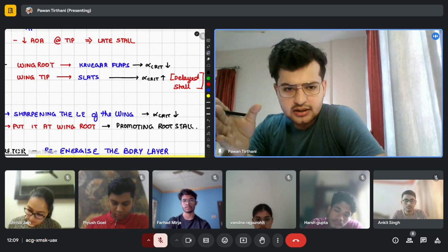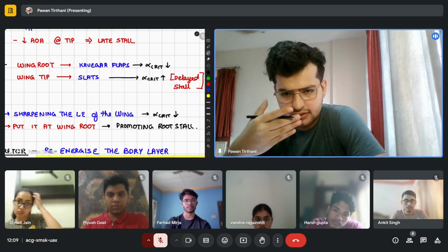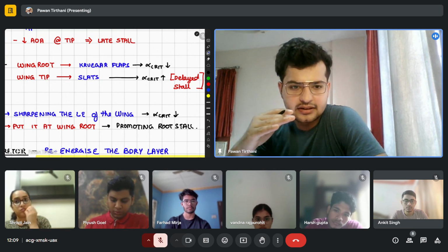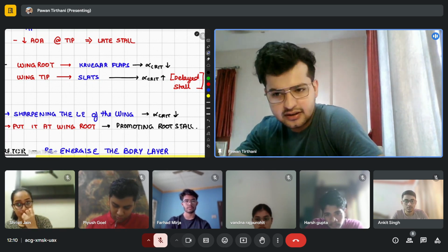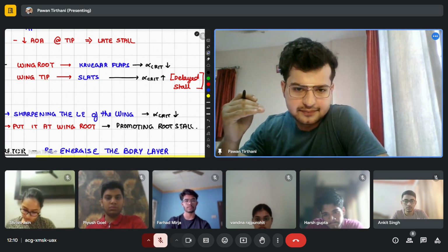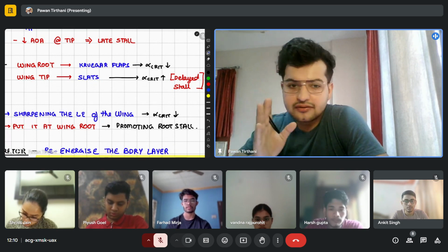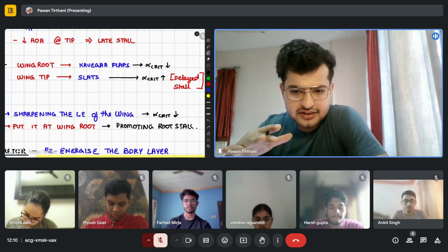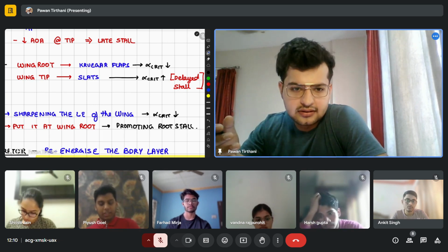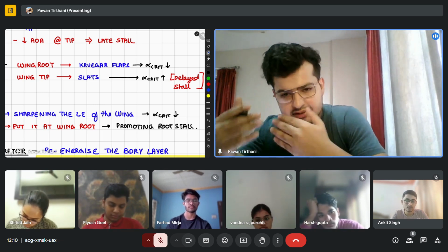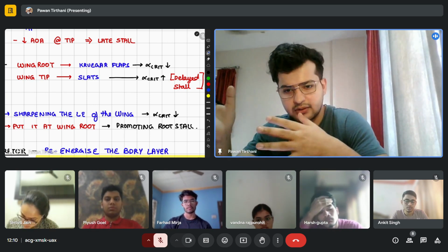जो आपका इंजन है ना, इंजन से फ्यूजलाज की तरफ जो भी लीडिंग एज डिवाइसेस रहेंगे, आप टेक ऑफ से पहले देखना, वो नीचे से क्रूगर फ्लैप्स बाहर निकलते हैं, and जो इंजन के उस साइड वाले टिप के तरफ वाले हैं, वहां से आप देखोगे स्लैट्स बाहर निकलते हैं 320 में। So what are we doing? When we deploy Kruger flaps, alpha crit doesn't increase much, it remains nearly the same, whereas on the other hand slats increase the alpha crit, right? We have seen this. So this is the reason why we keep slats at the tip section.